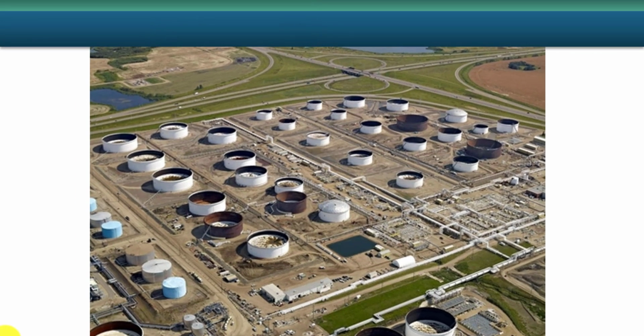Here are some examples of floating roof tanks. These are new because they're not coated yet. They will be coated. And I'd like to point out that you can see the mold and rust and crud on almost all of the floating roofs. That's because these are subject to direct UV radiation. They're horizontal surfaces, and it appears that they didn't use a good coating.